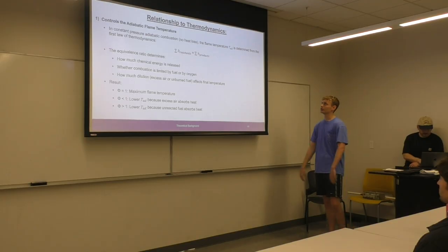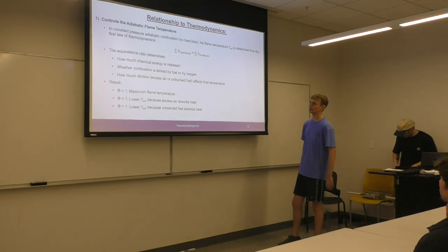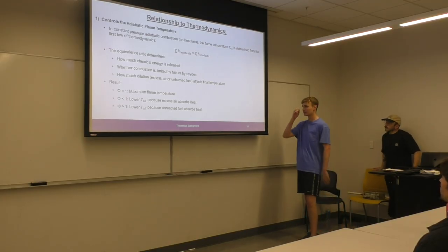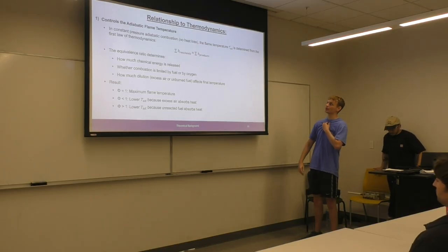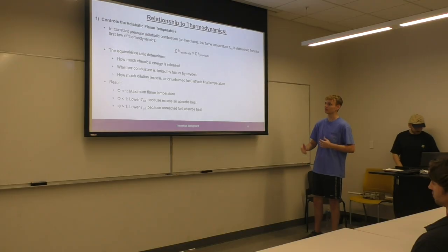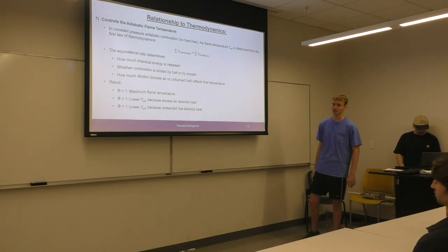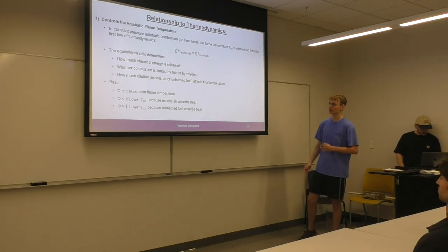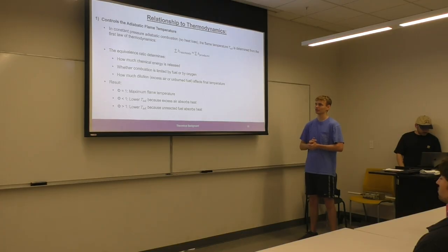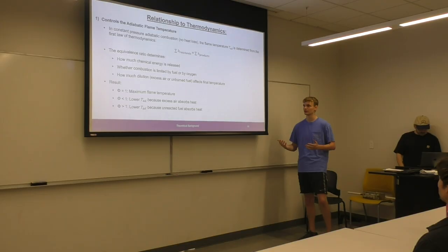With regards to thermodynamics, there's a big one in combustion study, which is adiabatic flame temperature. Again, this is an ideal process. At constant pressure, the adiabatic flame temperature is determined from the first law of thermodynamics, which is your H reactants equals your H products. The equivalence ratio will determine how much chemical energy is released, whether combustion is limited by fuel or by oxygen, and how much dilution, your excess air or unburned fuel, affects the final temperature.